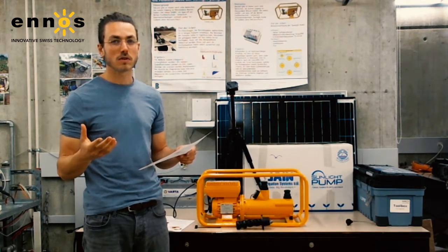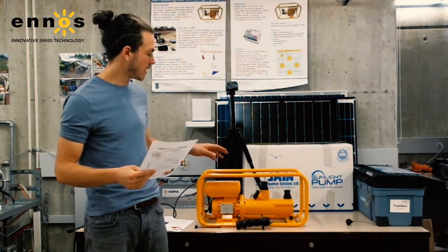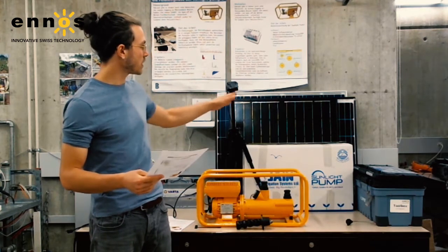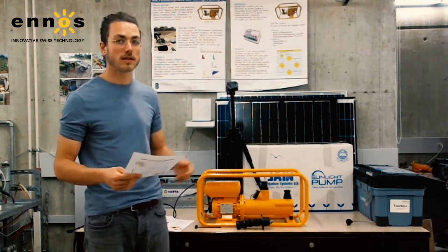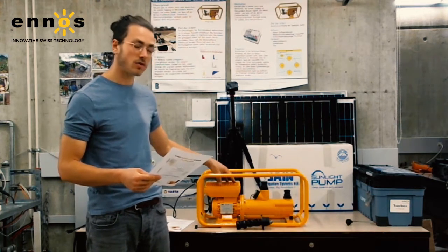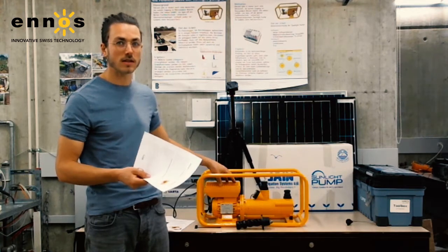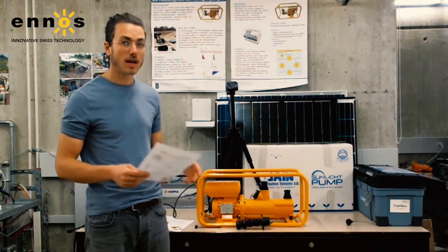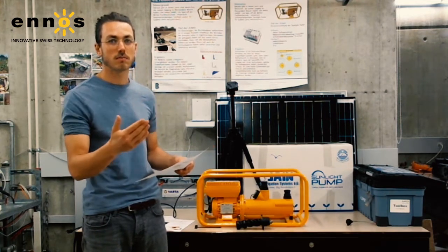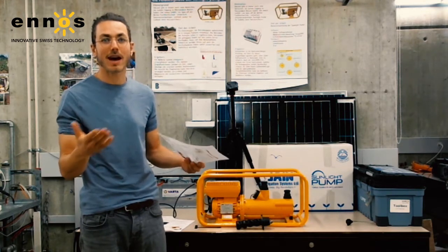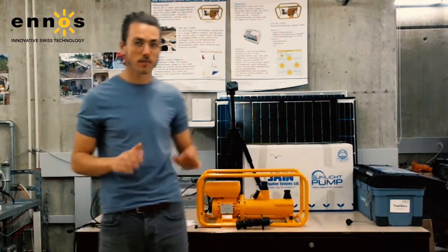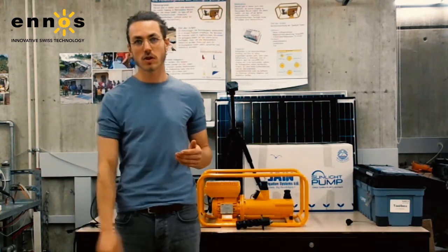And these 65 volts are the maximum that these electronics can take. That means that if your solar panels deliver more than 65 volts open circuit voltage, you will damage the electronics of the pump and potentially render it impossible to use. How can you find out if your solar panels deliver more than 65 volts, or how much open circuit voltage your solar panels deliver? You can check this almost in every case on the back of your solar panel.